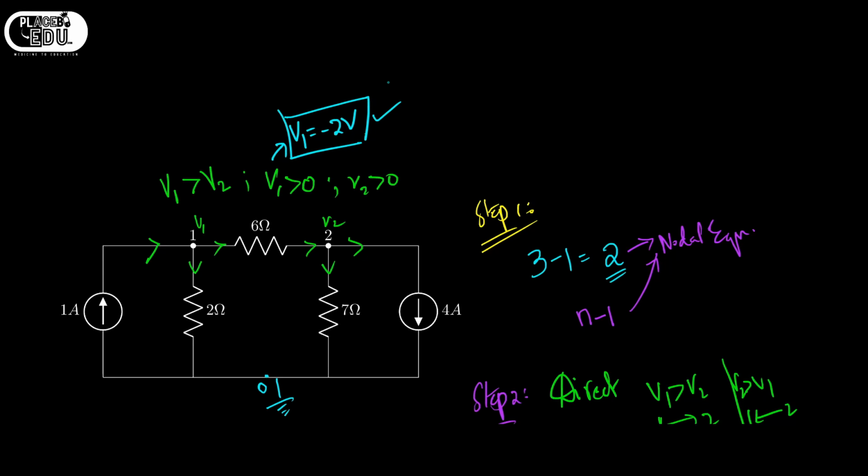You should remember that, because some people may think that if we take the wrong direction of current, we may end with a wrong answer. It's not so, because if you take a wrong direction, like I1 from 1 to 2, you will get I1 as a negative number. That's the important thing. Even if the assumptions are wrong, in this method you can continue.